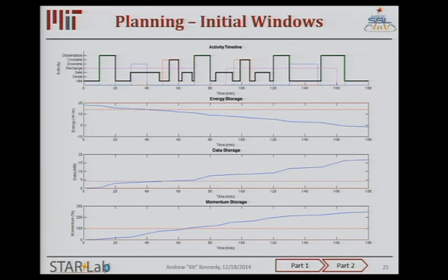Do you have a propulsion associated with this system, or is that just attitude control? With MiRaTA, to be clear. With MiRaTA, right? No, we don't. At this point, we thought it would be too complicated to add in propulsion, and we're already kind of packed in the bus and everything. And we don't really need it for our prime missions, so we don't have propulsion. But that would be something definitely interesting to add in the future. If you're going to do station keeping. Yeah, if we're going to do station keeping. Definitely a string of pearls orbit.